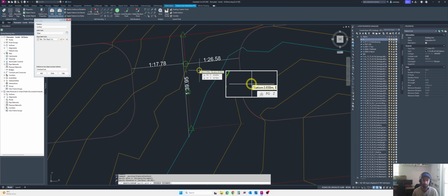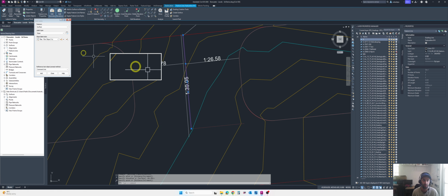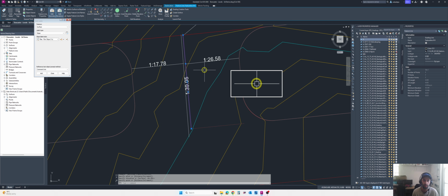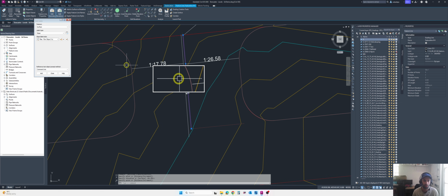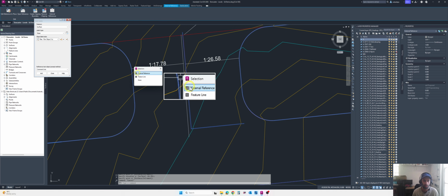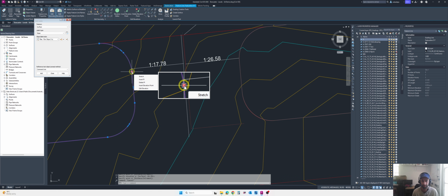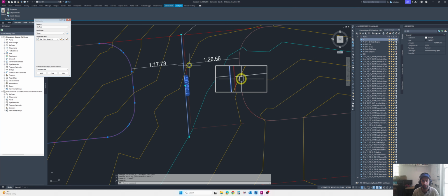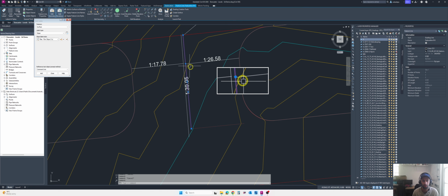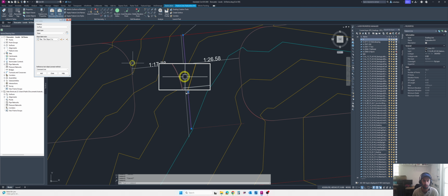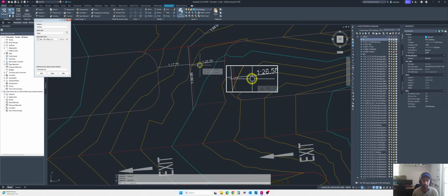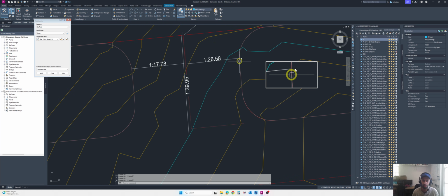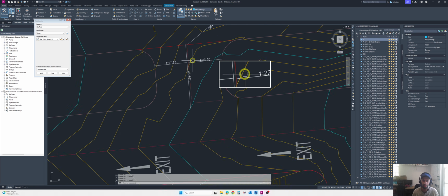These are all feature lines, not polylines. I hope you guys know about feature lines. Feature lines are different from polylines. This level is 38.392, and this one here is 38.193. What we can do here is lower this one, and if we lower this one, I think it would make a disturbance here.